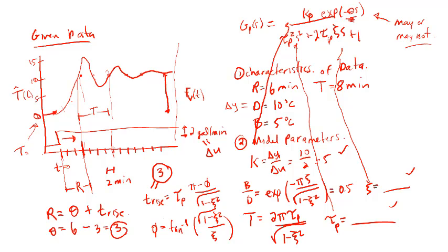The thing that I'll leave with is that if it were something that looked like this, we would assume this is a first order plus dead time model, because a first order model is always going to start off the sharpest at the beginning. If there's any sort of delay for a first order model, the assumption has to be that it has dead time in it.